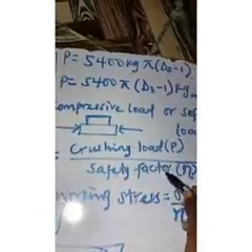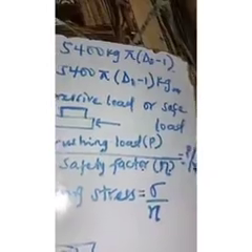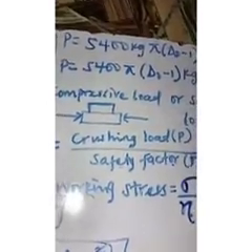So the compressive load, or safe load, is when it's shortened. You can have it as equal to your crushing load over safety factor, that is your P over your safety factor. You are given the safety factor in the question. So the working stress is originally your ultimate crushing stress over the safety factor.